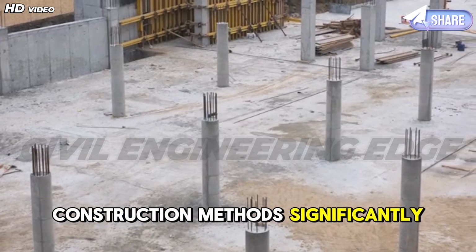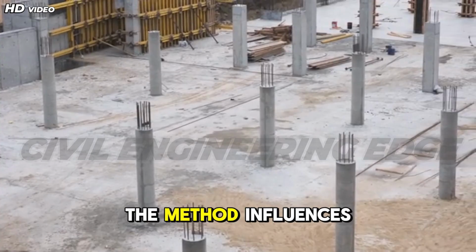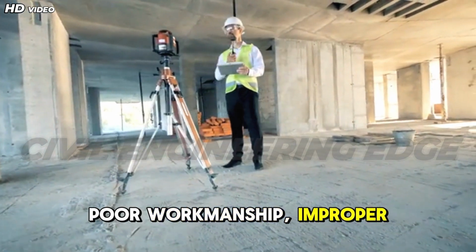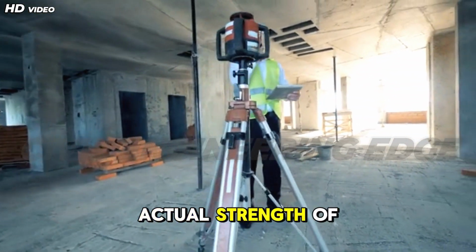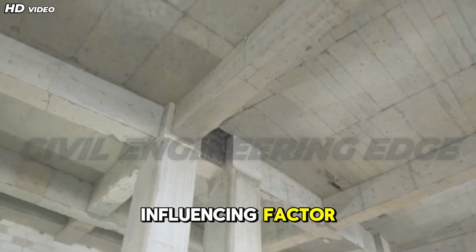Construction methods significantly affect column design. Whether the column is cast in situ or precast, the method influences detailing, reinforcement placement, and quality control. For workmanship, improper compaction or inadequate curing can reduce the actual strength of the column, even if the design is correct. Environmental exposure is another influencing factor.